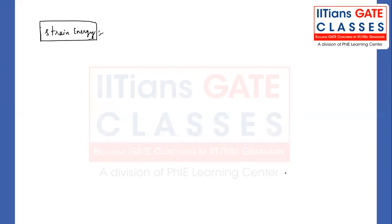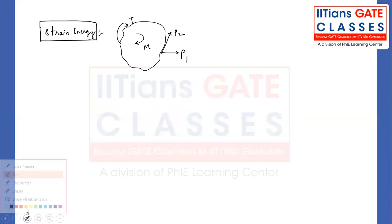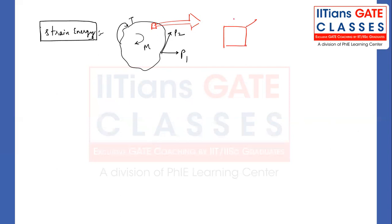Strain energy. Suppose there is a body which is being subjected to different kinds of load, like P1, P2, some kind of twisting moment, some kind of bending moment. Different types of load have been applied. But at a particular point, if I zoom in and say this material is being subjected to sigma 1, sigma 2, and sigma 3, then what is our strain energy per unit volume?